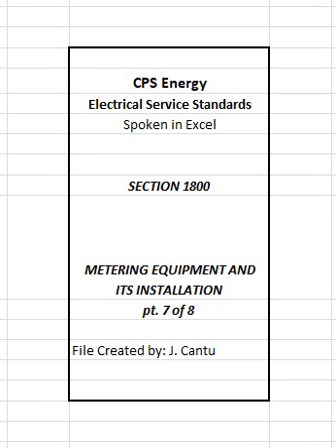1808 Adding meters for fire pumps. Where a fire pump is required to be individually metered, it shall be located adjacent to group meters on premise. Metering for fire pumps may consist of a self-contained or instrument transformer rated equipment sized for locked rotor, 6 times running load, amps.